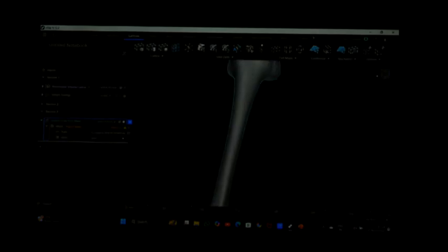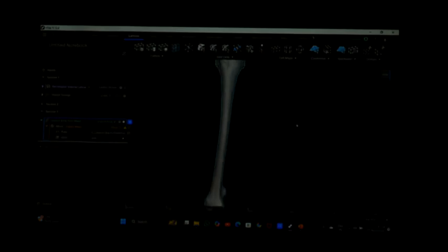So this is your bone. I want to cut it from here. In this portion I want to apply the lattice. So I will cut that bone. I will use Boolean subtract. First I will cut it, right? Boolean subtract. The primary body is this one. Primary body means the body in which we are applying it.